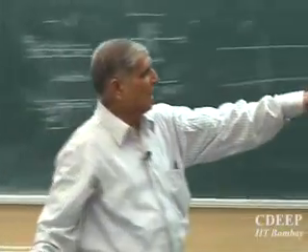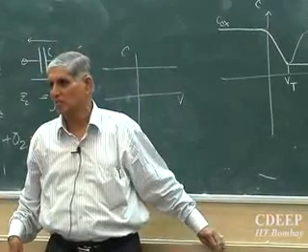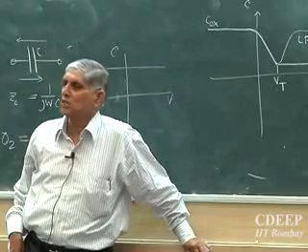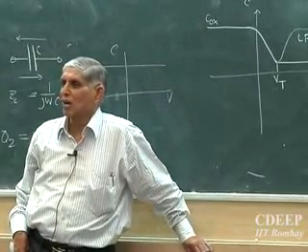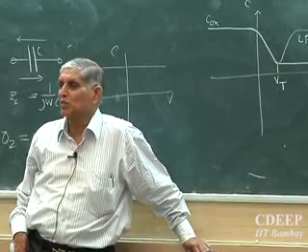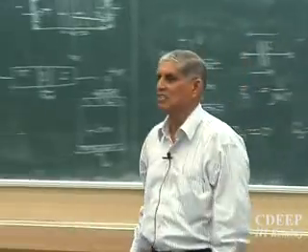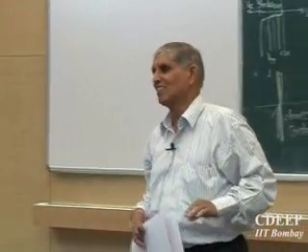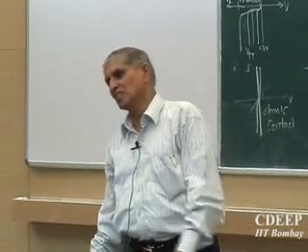What we will then evaluate, and what I am most interested in, is the threshold voltage, because in a transistor this value tells you below which current is not there and above which current is available. So I am very keen to know this Vt value. Once I know Vt in a MOS transistor, I will be able to get the currents, and once I know the currents, I know everything in a circuit. That's what I am interested in.